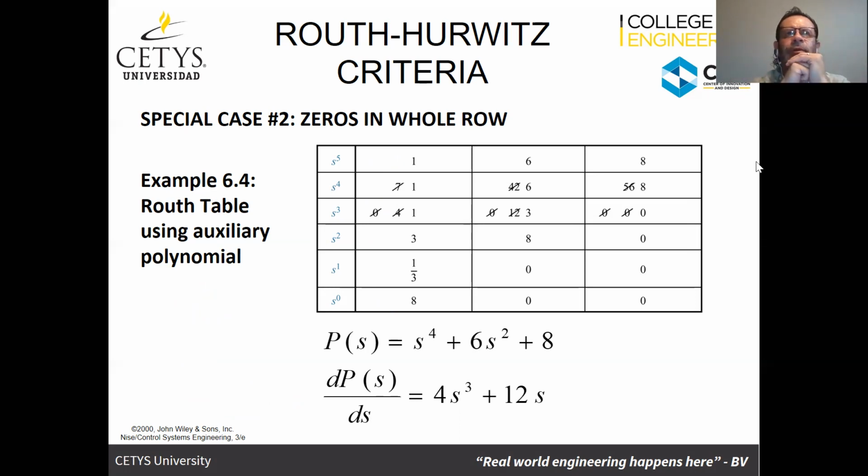We've got a transfer function. We want to identify if it is a stable or unstable system by looking at the number of roots that are on the right-hand side. However, we already know that if we just grab the characteristic equation and find the poles, we're also going to be able to do that without having to do the tabulation. So think about that.